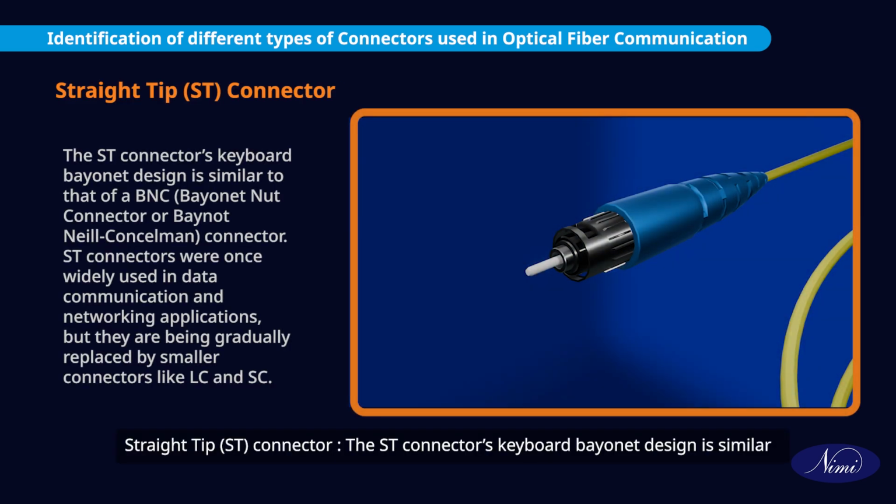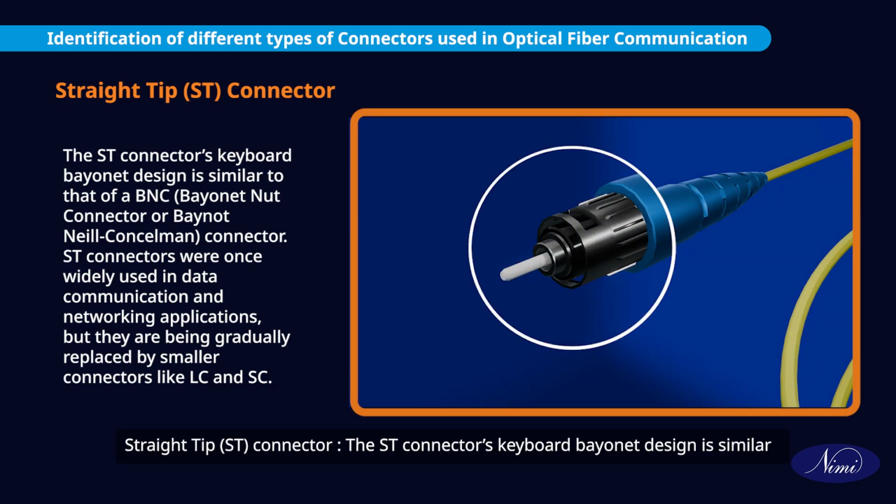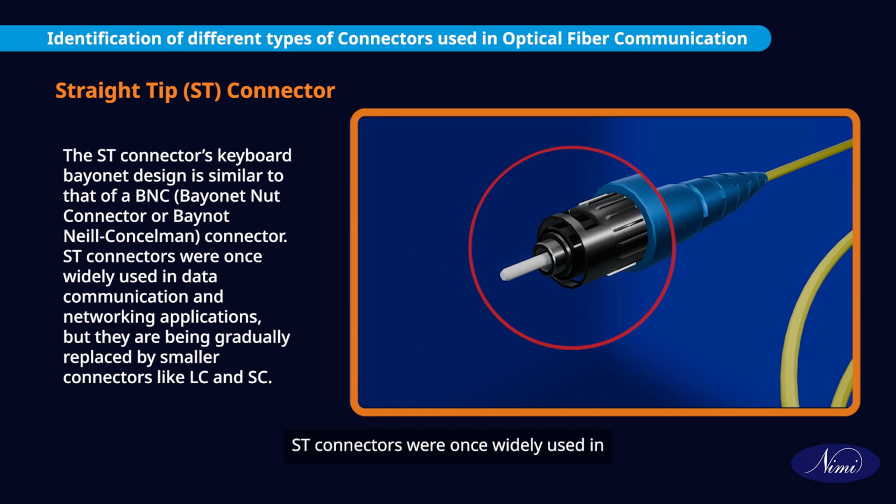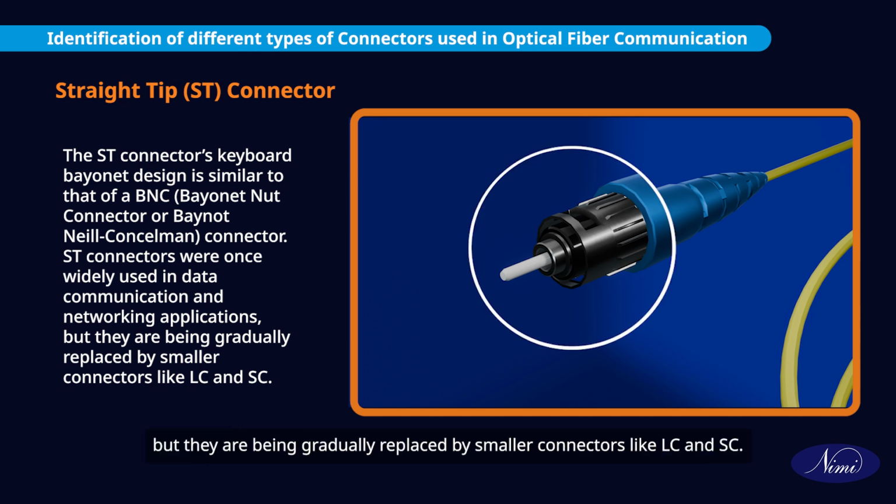Straight tip ST connector. The ST connector's keyed bayonet design is similar to that of a BNC, bayonet nut connector, or bayonet Neill-Concelman connector. ST connectors were once widely used in data communication and networking applications, but they are being gradually replaced by smaller connectors like LC and SC.